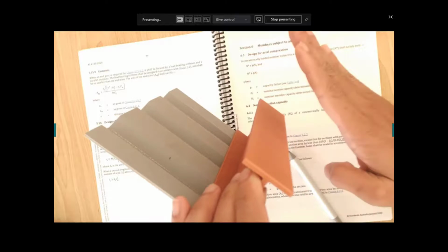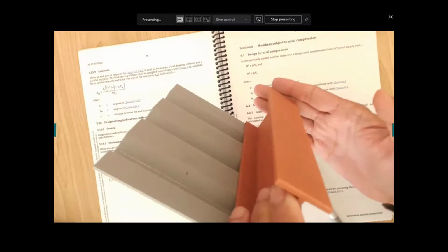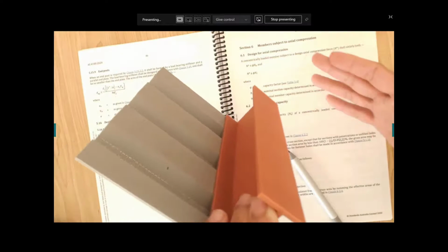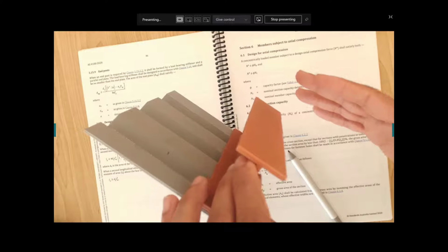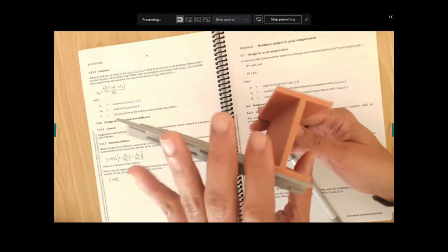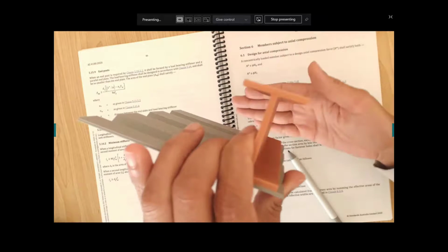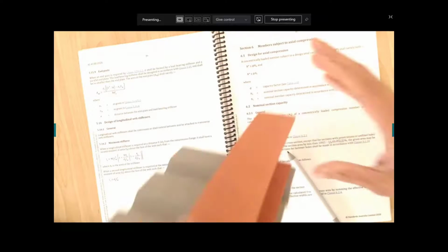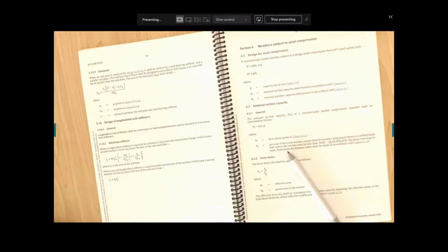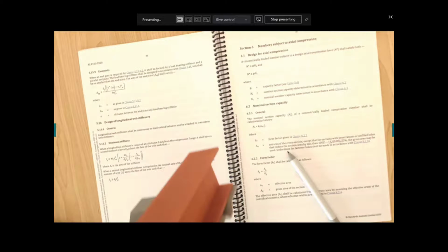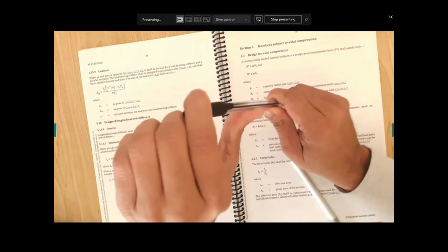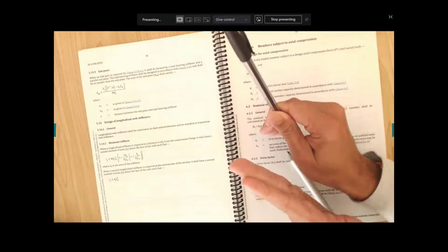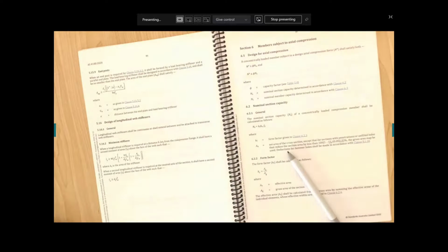Like in the beam, do you remember there was lateral torsional buckling? When there is member buckling, a magical equation came into the picture, and you have this lateral torsional buckling, not of the sections. The same here, you have this global buckling. Global buckling means it will do this. I don't have that form, so how can I show you? Yeah, let me show you with this pen. This pen will just do this global buckling, not the local buckling, if it is long.